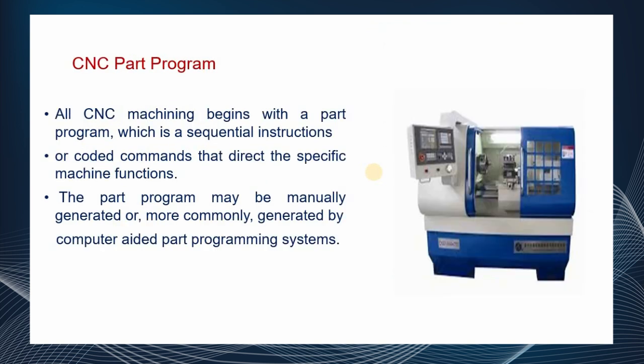CNC part program: all machining begins with a part program, which is a set of sequential instructions or coded commands used to direct specific machine functions. The part program may be generated manually, or more commonly generated by computer aided part programming systems.